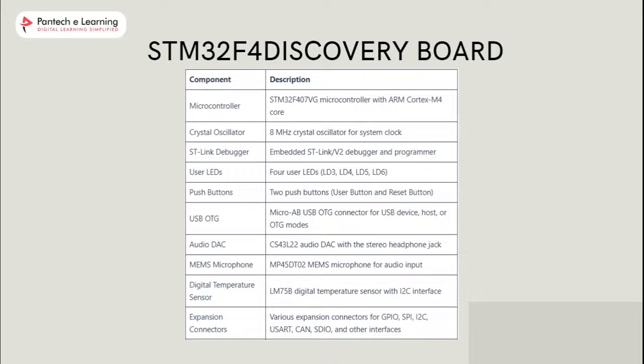The STM32F4 Discovery Development Board uses the STM32F407VG microcontroller. It has multiple peripherals including USB, SPI, I2C, CAN and SDIO, so many protocols.